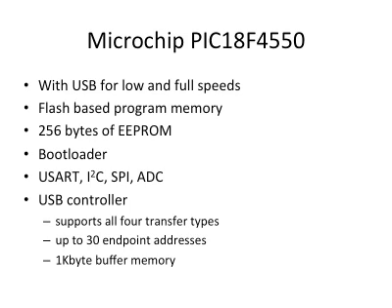Bootloader is specifically for that purpose. So with the bootloader, if you have, for example, an RS-232 interface to that microcontroller, you can set the chip to operate in the bootloader mode.